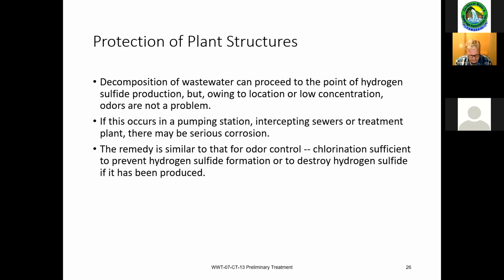If you're dealing with odor control, and if you're adding a nitrate-based product such as Bioxide, depending on your treatment system, you need to be really careful. We add a lot of Bioxide throughout our collection system, but it's all at as minimal a dose as possible.